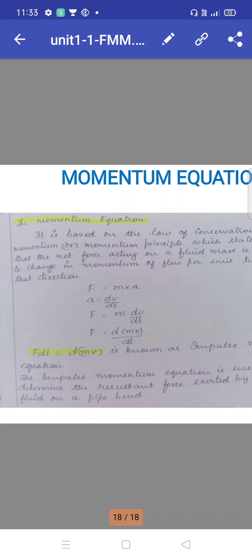Momentum plays a major role in the rate of flow in bent pipes. That is very essential, and needs to be analyzed much more carefully than a normal or straight pipe. Bending means the direction changes, and due to the change in direction of the fluid, some eddy formation also occurs.